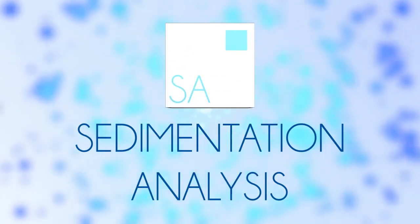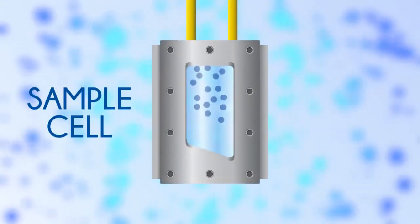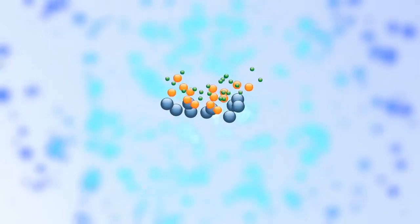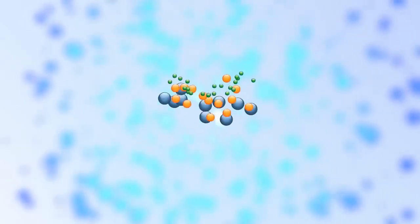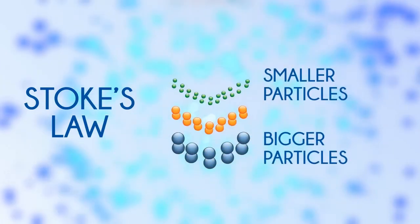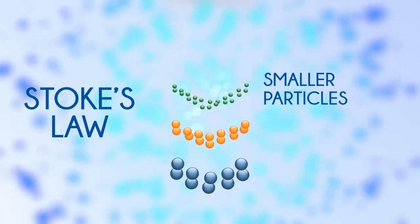Sedimentation analysis. For direct measurement of highly concentrated slurries, sedimentation analysis by X-ray absorption can be used. This technique directly measures the terminal velocity of particles and, using Stokes' law, determines absolute mass and size.